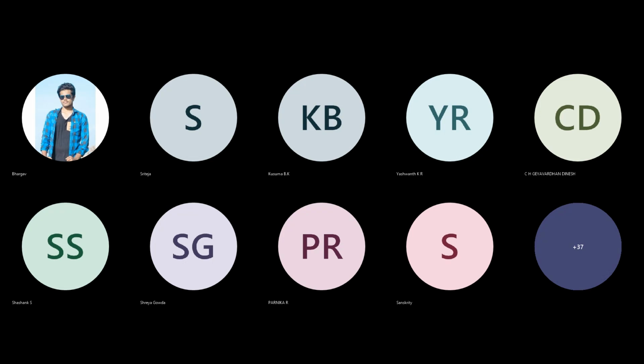The loop gain A beta must be positive, that is, the feedback signal xf should have the same sign as xs. If, as is the case in many circuits, the loop gain A beta is large, more than 1, then AF is 1 by beta, which is a very interesting result. So let us see how exactly it works.